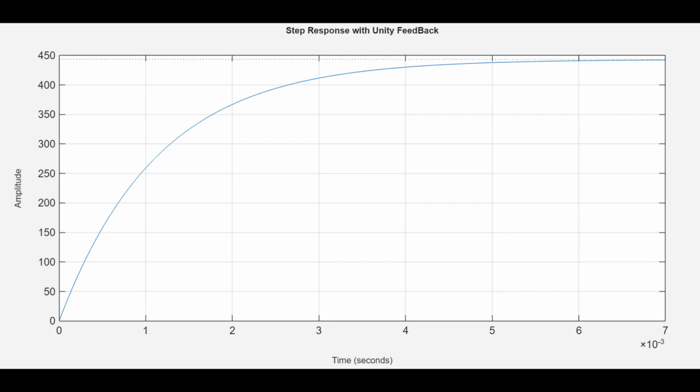We then plotted the step response of the system using the step command in MATLAB, scaling the system by the reference omega, since the input is no longer voltage, but a reference speed. We then used MATLAB's control system designer, opened with the rltool command, to evaluate how the system would perform under the design requirements of less than 5 second settling time and less than 10% overshoot. From there, we decided on our own stricter requirements of less than 2 second settling time and 0 overshoot, and we designed a PID controller using PID tuning within the designer. The PID controller was exported as a MAT file so that it could be loaded directly into the analysis script without having to redesign it every single time.